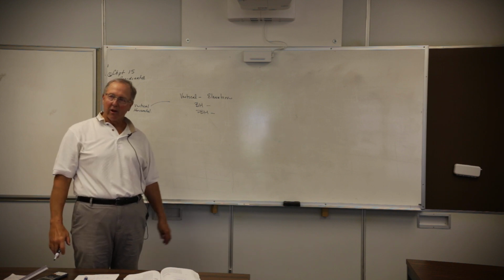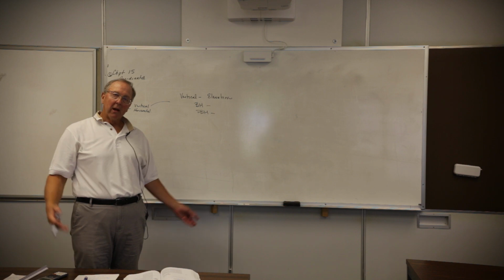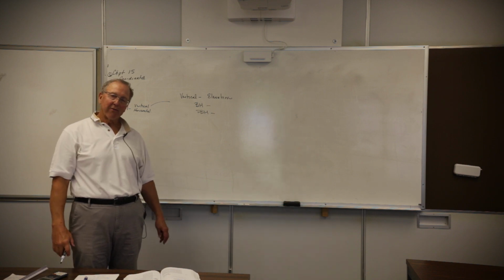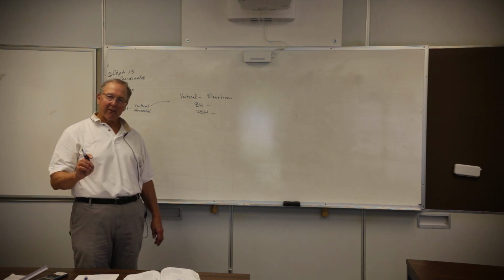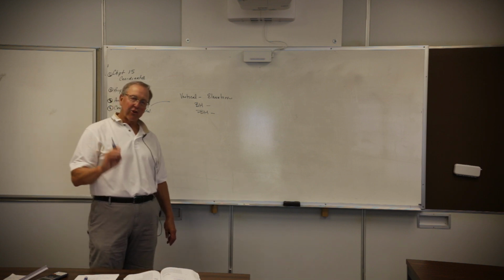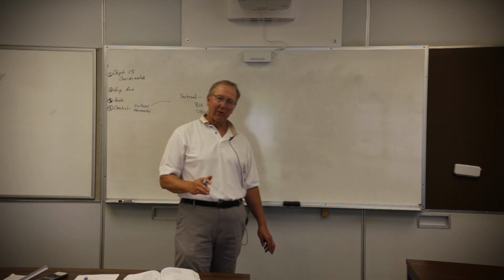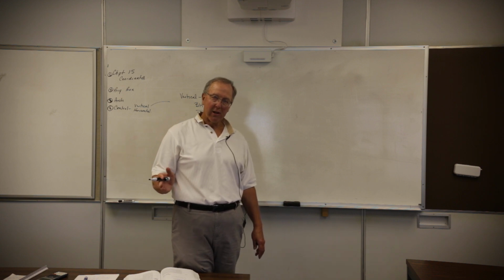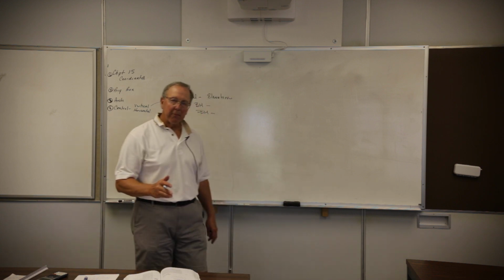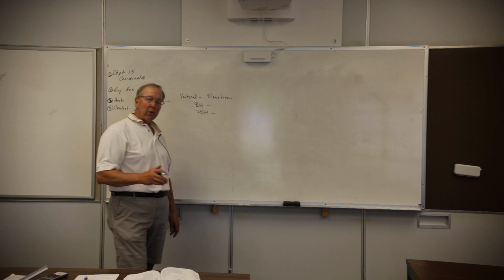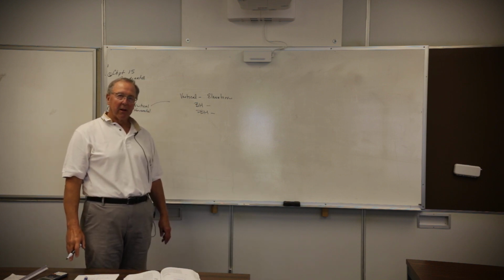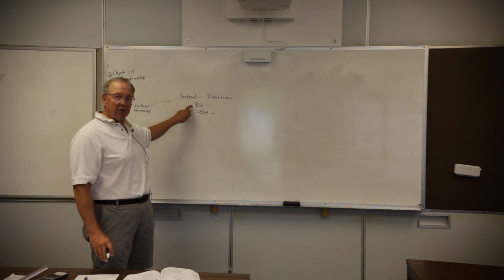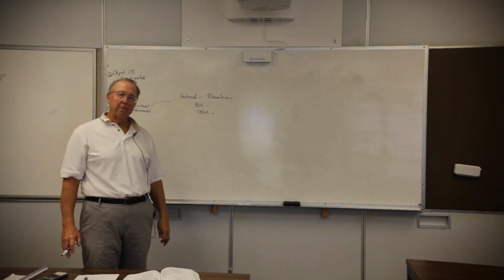A lot of times they'll use 100.00. Your first floor may be at 102.5. So all you have to do is make sure you've got a site benchmark that you can access easily, that is not disturbable. Somebody can't come out and mess with it and change it and screw everything up. And make sure that you index off of it and that everything is relative to that benchmark, whether it's the big guy, the USGS, or whether it's a site benchmark.